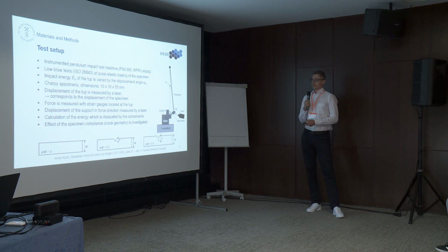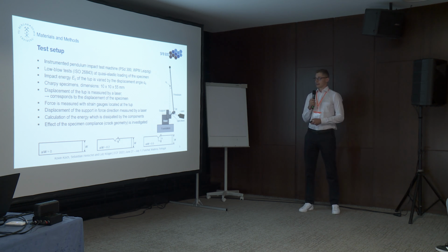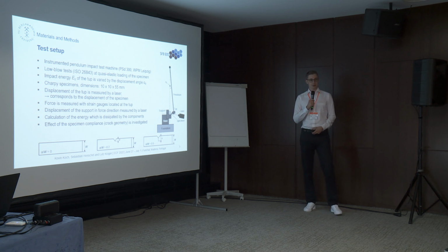specimen is placed on the support. The support itself is connected to a steel base, and the steel base is then set on a concrete foundation of high mass. In the test, the displacement was measured at the tup with a laser, and the displacement of the tup corresponds to the displacement of the specimen, which is later needed for the energy calculation.